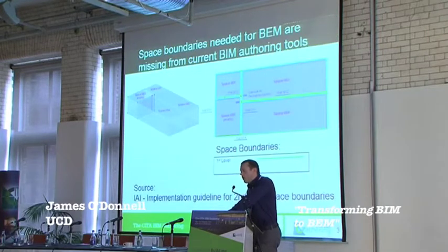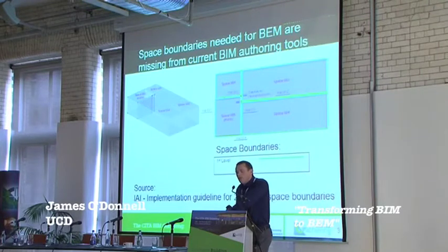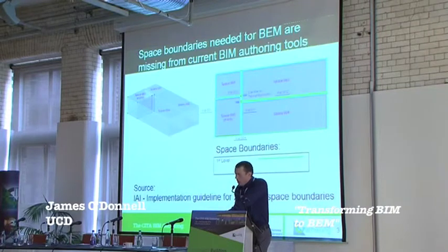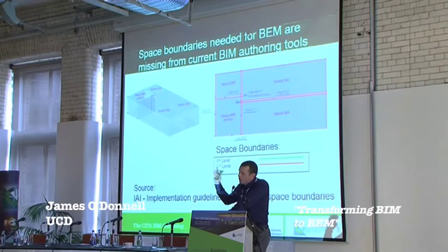So with this in mind, zone boundary or space boundary, it's the same thing in this context. The required space boundaries for energy simulation are not exported by the current day CAD tools to the IFC data format. So all of this work is based on the IFC open data format. So in essence, we have a single boundary that surrounds this room, but when we break it down into detail, we require second-level space boundaries that represent the heat transfer surfaces. So that's an individual space boundary per wall, window, door, floor, ceiling, column, etc.